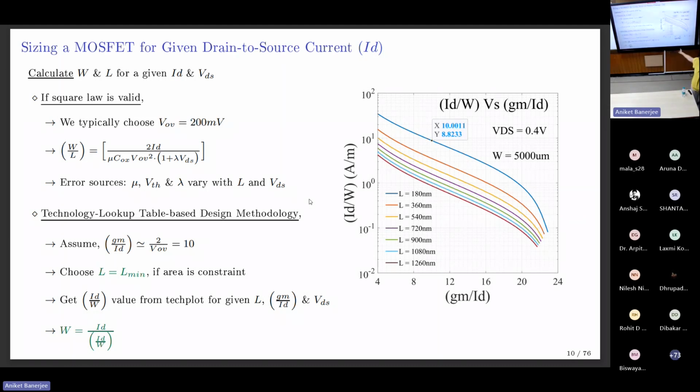Understand the LDO first. In our case, also think of the load varying the pole frequencies. If we had said, let me sweep the load, that doesn't help you. Same way, if you're designing a telescopic amplifier, you can create a bound on it. For our case, we're very sure about the range of VDSs that we will supply. It will still have error, but you will get to a very good ballpark number, way better than square law. I remember the errors that we saw were sub 10%, which is huge for a designer's first go, compared to square law at 45%.